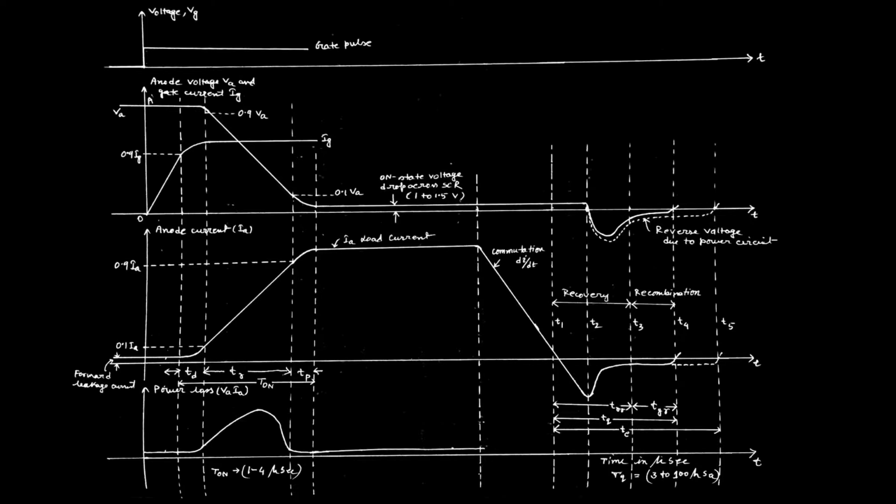It can switch on again with a lower breakover voltage, due to which a few switches can be short-circuited. That is not required. That is why, to maintain a reliable turn-off, always try to maintain the time up to TC, the total turn-off time.